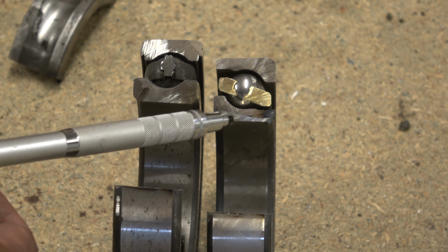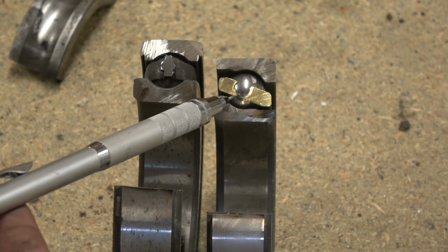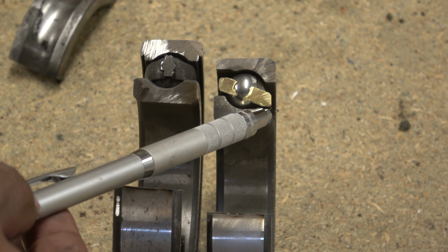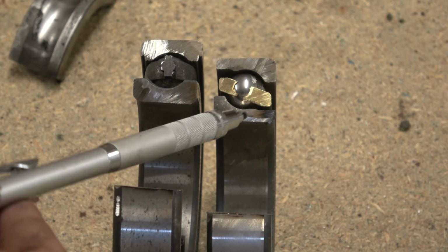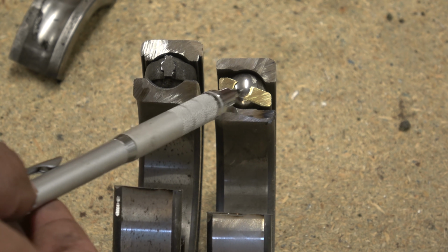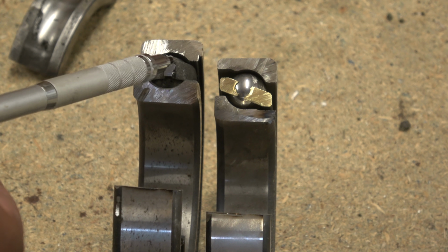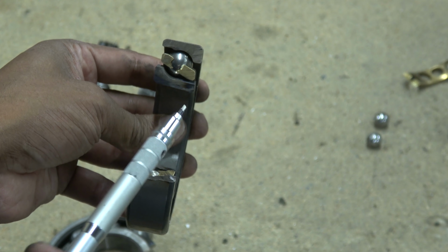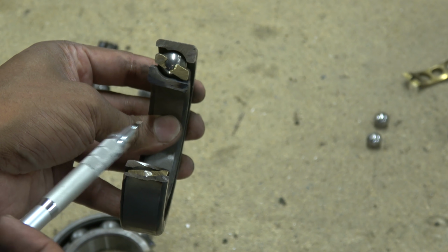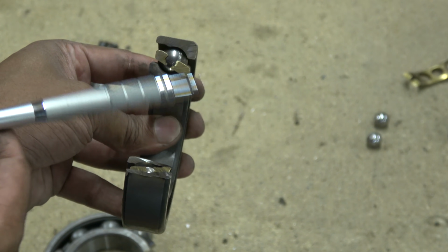The angular contact bearing is clearly asymmetrical, so you've got a huge lip on this side, nothing on this side, huge lip on this side, nothing on this side. You can also clearly see the brass metal cage, whereas on this one you've got this pressed riveted cage. This angular contact bearing can only take load in one direction, so it can only take load that way, so you have to preload it that way.